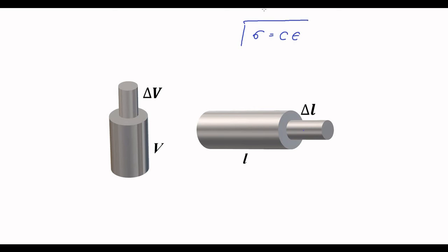Okay, whether it is volumetric strain or longitudinal strain, bulk modulus or Young's modulus. So Young's modulus or bulk modulus, that is already known. This stress that is given through the EMF signal as per Faraday's law and magnetostrictive effect is given in terms of volt or current, that we convert into appropriate units, Newton per meter square or Pascal or whatever units is there through the specification sheet.